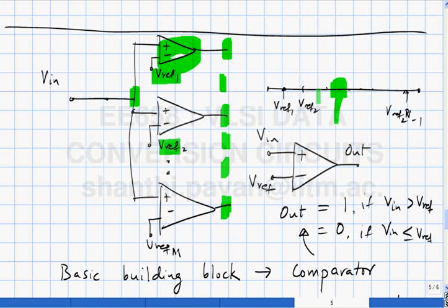If you see the advances in flash converters, you will find that most of them are from ICs designed for disk drive read electronics, where the speeds at which you read data off your hard drive keep increasing with time. 10, 11, 12 years ago when I was working on this stuff, the speed was about 700 megabits per second. Today the speeds are close to 2 gigabits per second. So you can see that there's a 3x improvement in data read speed.